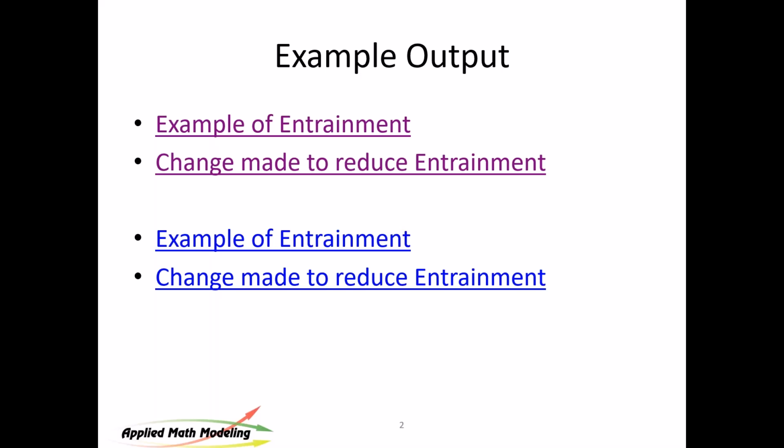Is the CoolSim software a modeler and a solver? Yes, it is. It does both. We both create the model and solve it. That's the point, and I'm going to show you some solutions here. And the mesh is automatic. We automatically mesh these. So all you do in CoolSim is once you set this thing up, you press the go button and it meshes.